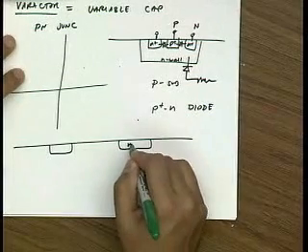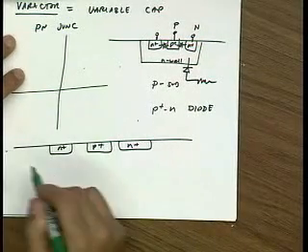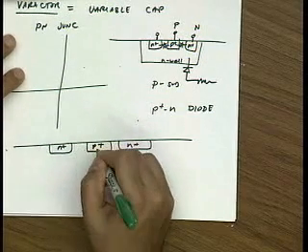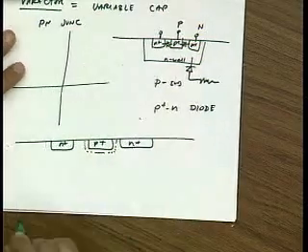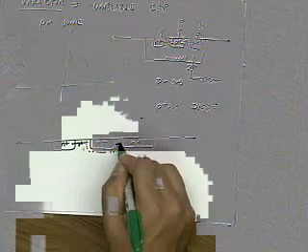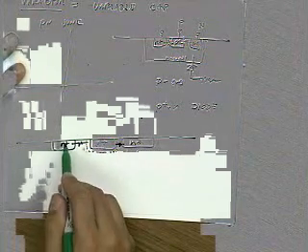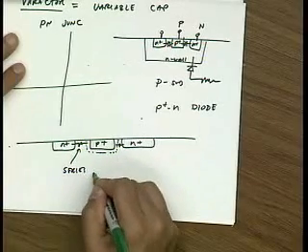This structure is N plus, P plus, and so the actual capacitor happens over here, right? It's this depletion region. This is just the extra distance we have to move to get to this contact, so this introduces some series resistance.